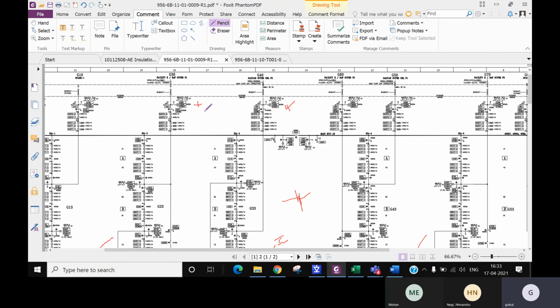So two cases you can perform: one is by energizing the cable VT, and the second one is the line VT. Then you check the voltage over here, what the overvoltage is. There is only the energizing case, no de-energizing case. So these are the basic cases you have to do if your client asks for ferroresonance.